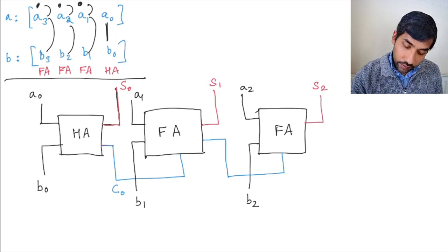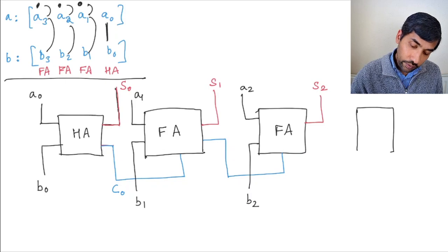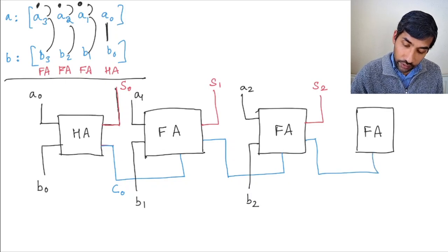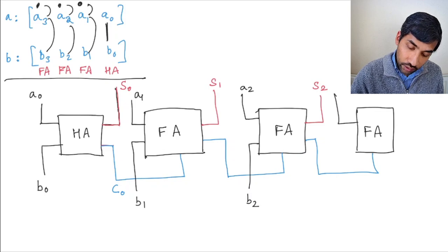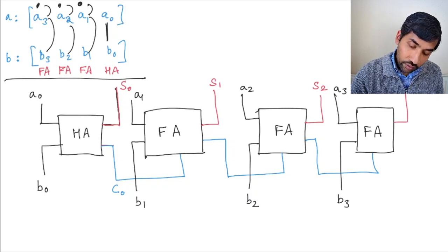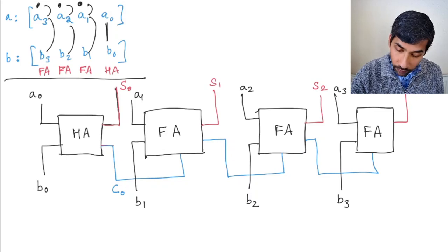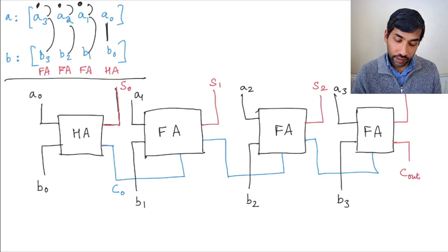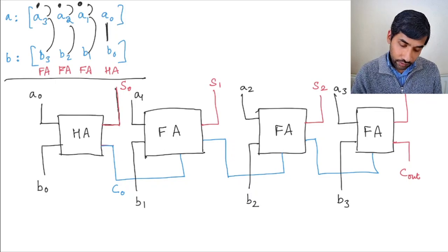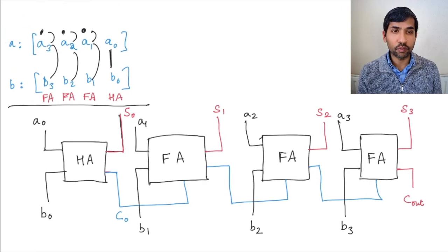That's again a full adder whose output is going to be S2, and you have another full adder built here, and you can connect the carry from here to this place, and you'll have your A3 going in here, you'll have your B3 going in here, and you'll have the sum bit S3 coming here, and you will have an output which is C out, the final carry. So that makes a 4-bit adder. I see that I've just occluded some things here, so I'm just pulling this down.